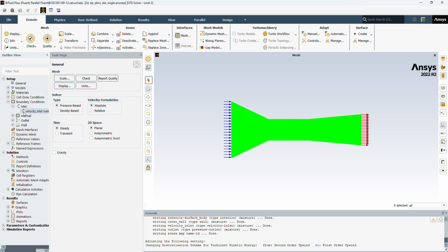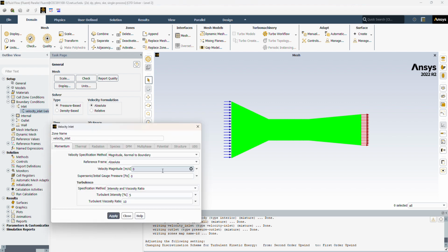Then we're going to mess with the boundary conditions. At the inlet, we want the inside of the actual wind tunnel to have an average free velocity of 15 meters per second. Using the contraction ratio, we are able to get that the velocity at this inlet should be this number in order to have that 15 meters per second velocity there.